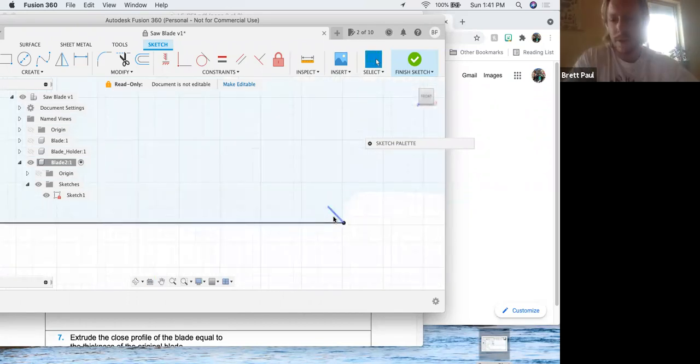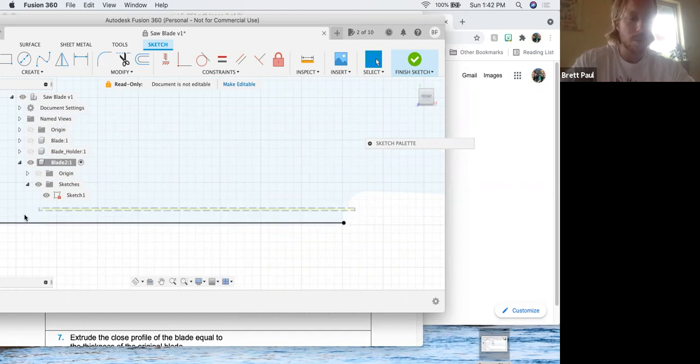We've kind of covered this already, but just to reiterate, construction lines are visible within sketches, but they're invisible when it comes to extruding or creating a third dimension off of a 2D sketch. So once you've exited the sketch, construction lines are then invisible to extrude tools, which is the whole point.